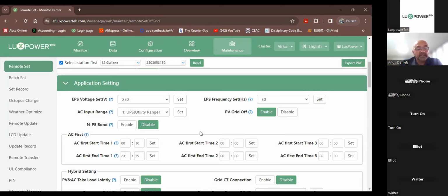Not terminal electrocution, but you could have clients complaining that, for instance, when they touch a tap or have a shower, because the bonding on the copper piping is not done correctly, they might pick up a voltage on the earth. So it's important that you do the neutral earth bonding.